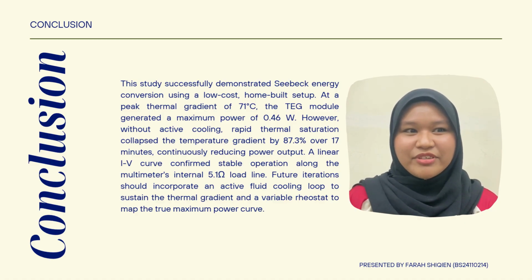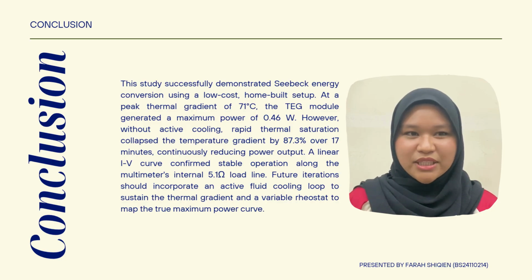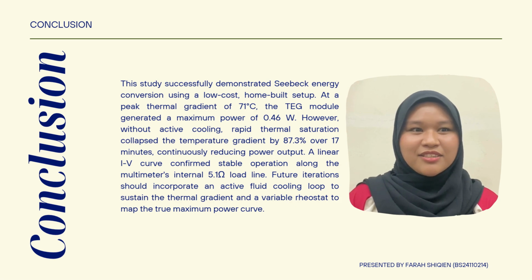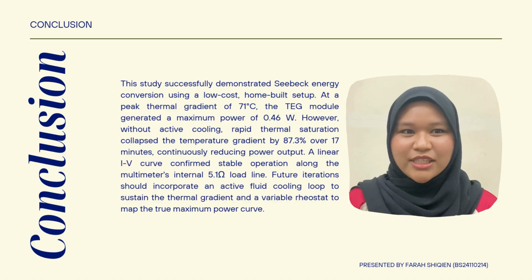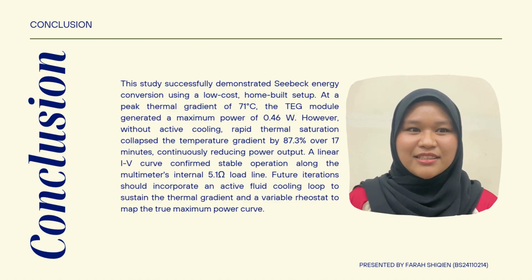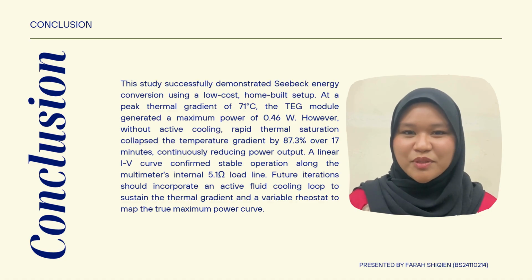A linear IV curve confirms stable operation along the multimeter's internal 5.1 ohm load line. For future iterations, we should incorporate an active fluid cooling loop to sustain the thermal gradient and a variable rheostat to map the true maximum power curve.